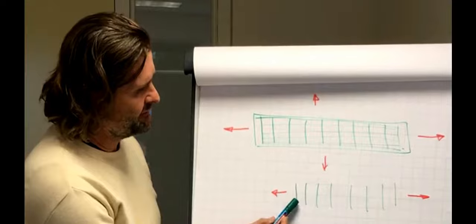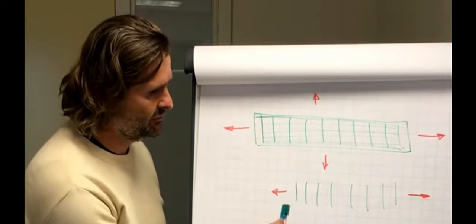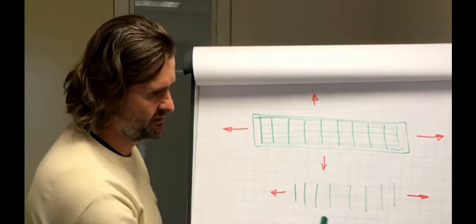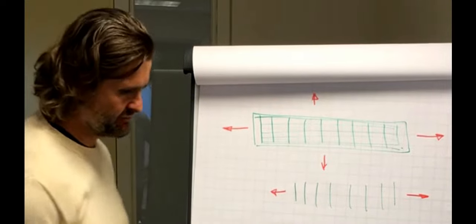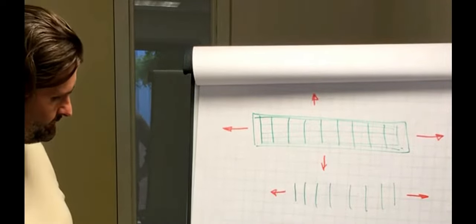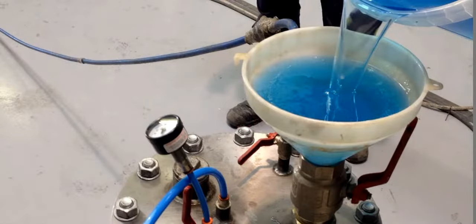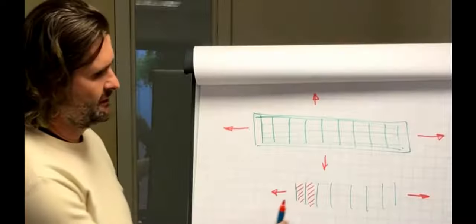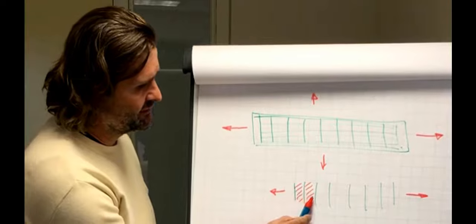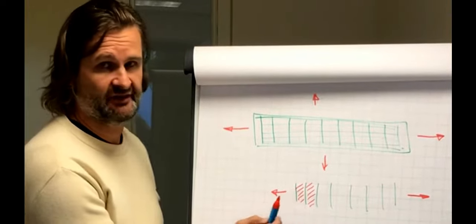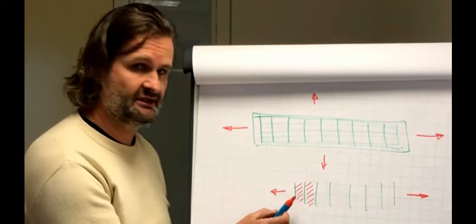That means that the fibers that are in the wrong direction, so in the layer that has the vertical fibers, they will be moving outward. They will be stretching in this direction, in the horizontal direction. But there's nothing to keep them together inside this layer, except for a little bit of resin in between the fibers. So basically, the material's elongating, and there's only the resin keeping the fibers together. The fiber itself is not strengthening it in the proper direction in this given layer.